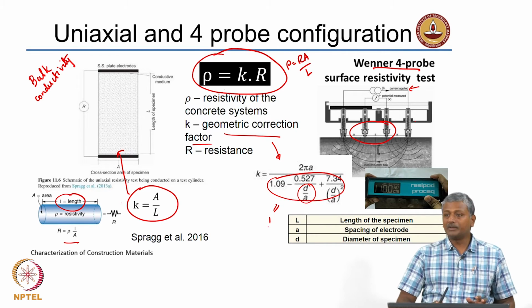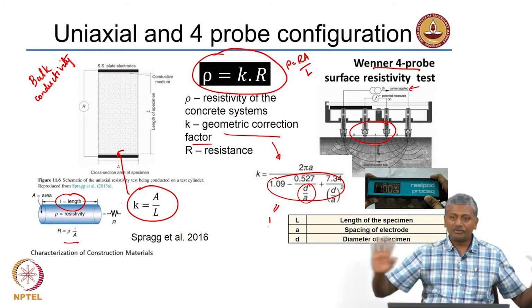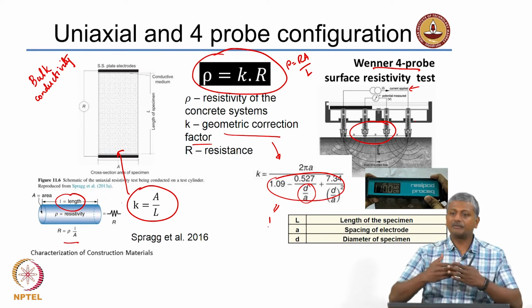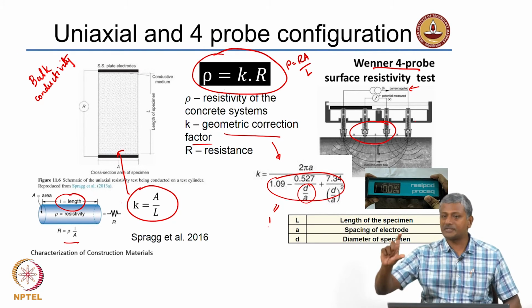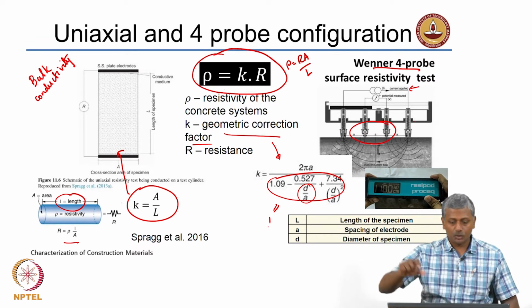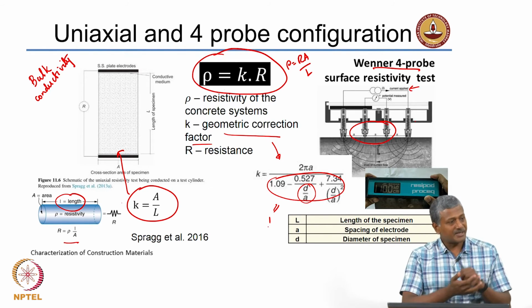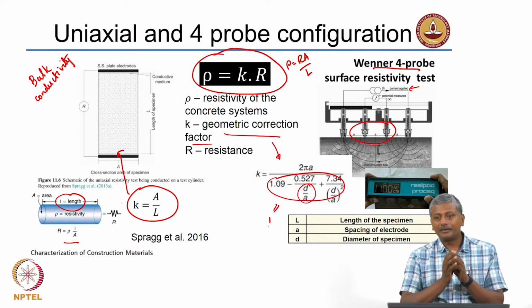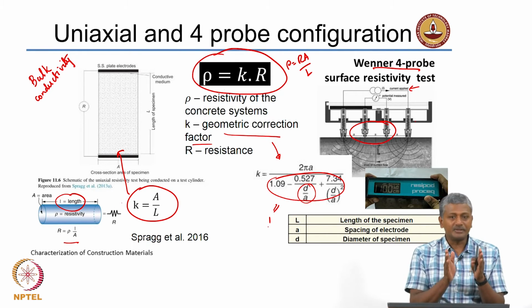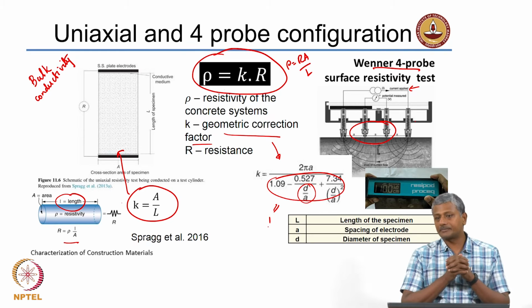Now, you need to remember that very often we do not really conduct the experiment on infinite or rather very large thickness. We have specimens that have finite thicknesses. So, you may actually have effects built in because of those finite thicknesses, which is why we need to use specimen sizes which are at least 3 to 4 times the spacing between the electrodes.